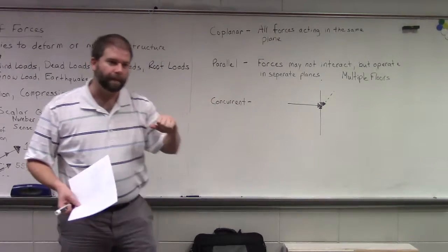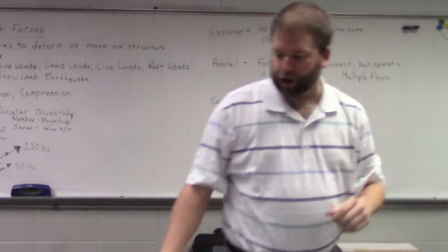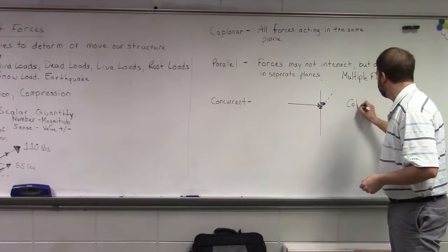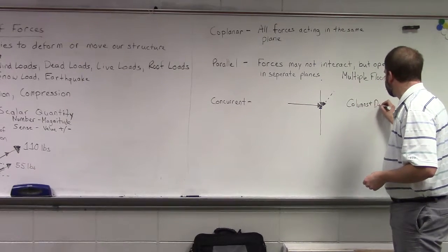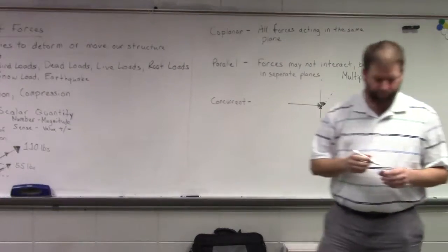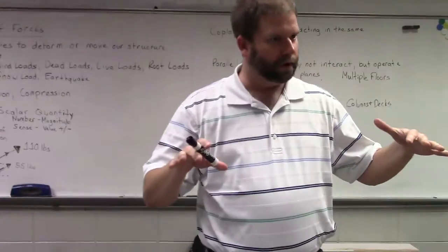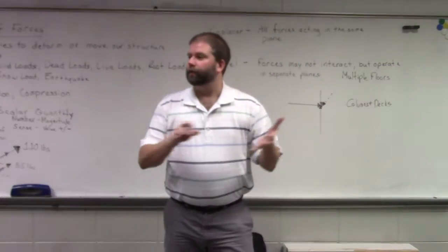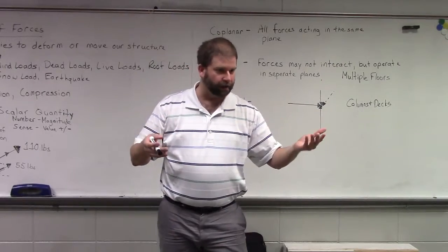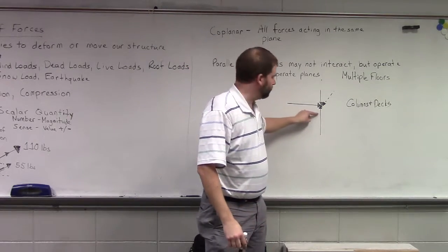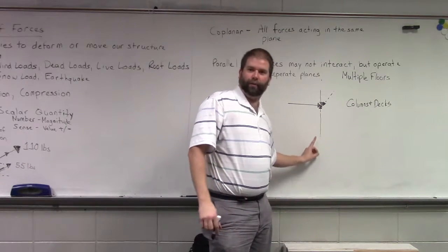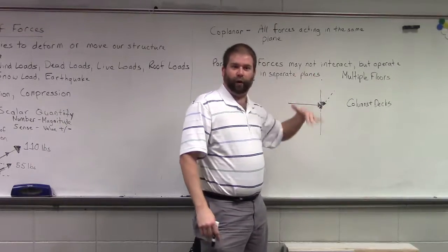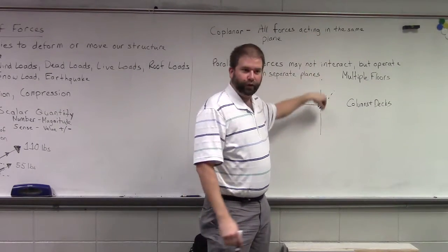Okay, so what would be concurrent? An example of a concurrent force would be if we took a system of columns and decks. Okay, so our decks are going to have first the force from their own weight, so they need to get that down to the ground. So they'll be pushing that along. They'll be pushing along any of their live load. So that will come along the deck to our column. Our column will be also providing resistance that's being pushed back up from the ground. And then if there are any floors above that construction, that will also be transmitting load.